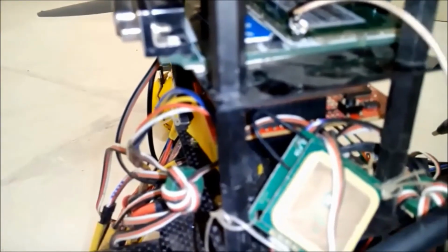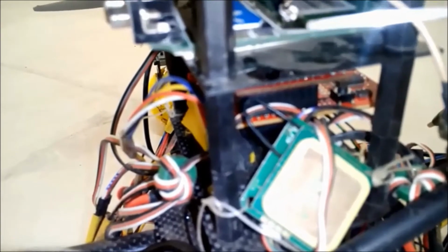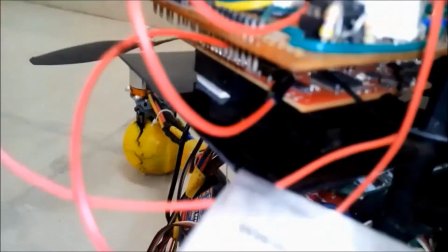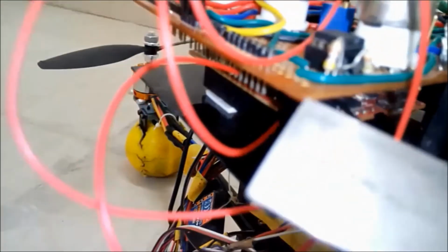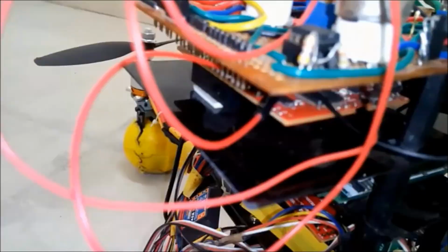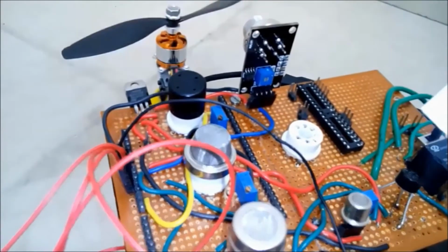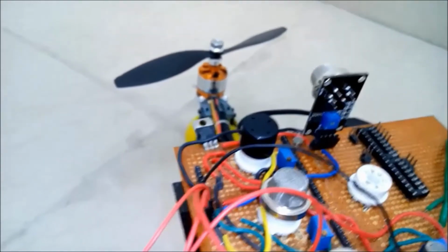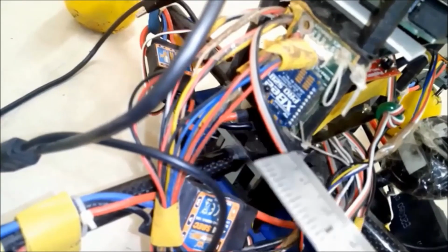This GSM module sends the atmospheric gas concentration, percentage vegetation, and tree count in a locality to the base station. Above the GSM module, we have another TIVA Launchpad which reads the analog data sent by the gas sensor module and sends it serially to the BeagleBone Black. And at the top, we have the gas sensor module which measures carbon monoxide, carbon dioxide, ammonia, methane, ozone and hydrogen in the atmosphere. This XBee is being used for wireless telemetry.